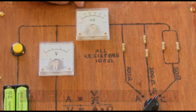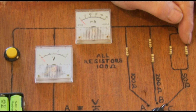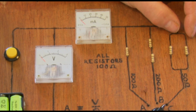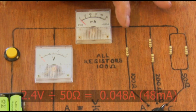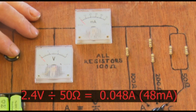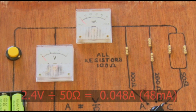And if we have two 100 ohm resistors in parallel, then the total resistance of the two of them will halve. So that means it's 50 ohms. This time we're going to see double the current that we had with the 100 ohms. There it goes. It's about 48. Got a bit of a dodgy switch here. I think that needs changing.